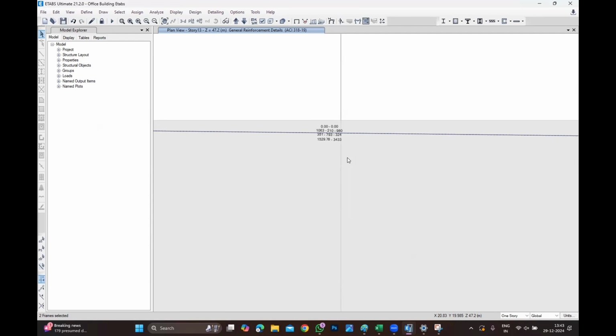If you misunderstood the concept and try to increase the depth, then even if you increase twice the depth, it will not satisfy, because the problem is under width. There, even if you increase the width by 25 millimeters, it will pass, because it is a matter of width. In flexure, if you try to increase the width, even 100, 150, 200 millimeters, it will not pass.